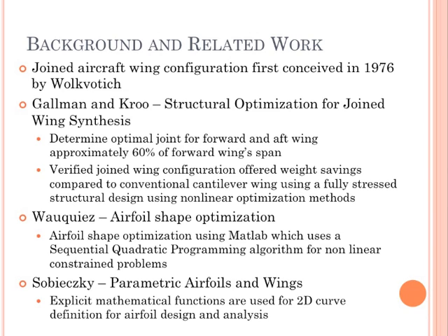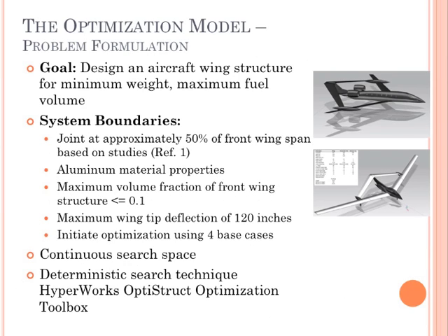For this project, an airfoil shape optimization was also completed, which minimized airfoil drag and maximized volume. The analysis was completed using a MATLAB program I found on the MathWorks website. It used a symmetric airfoil as an input, and it runs through an airfoil parametric analysis to determine its performance, and then uses a conjugate gradient method to optimize the airfoil shape.